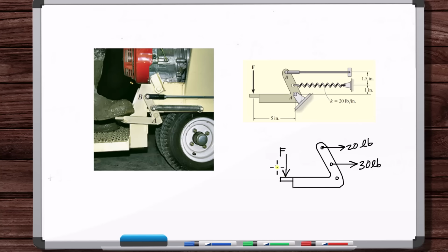But if you had to, you could put it at an unknown angle, or you could solve one free body diagram with the foot acting straight up and down, and then one acting at a 45-degree angle. You could do it that way. But what is nice is that when it comes to the sense of unknown forces, so the sense being, is this positive or negative, acting up or down? As long as you put your known force information in correctly, the final answer will tell you what the correct sense is. If you put the wrong sense, then the final answer will be negative, so you'll know the force is actually acting in the opposite direction of which you put it.